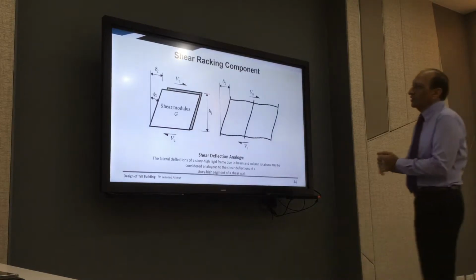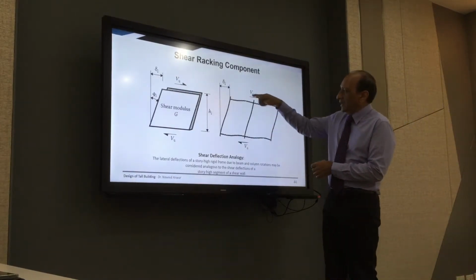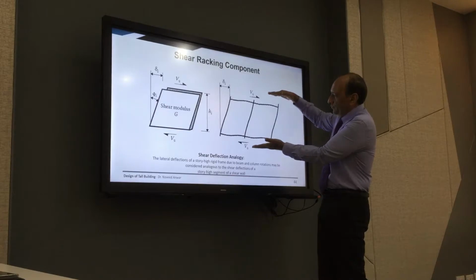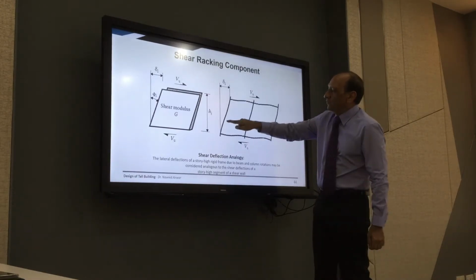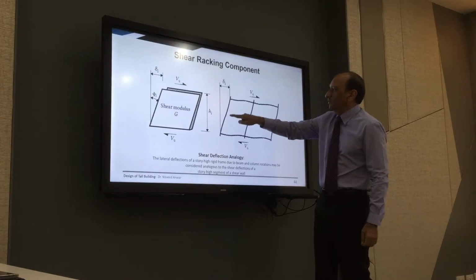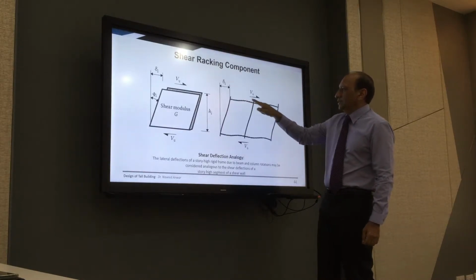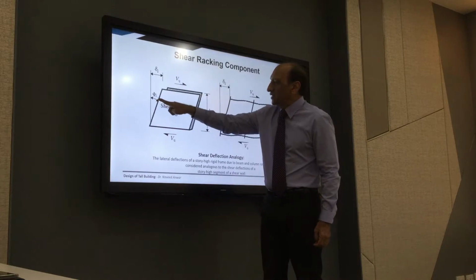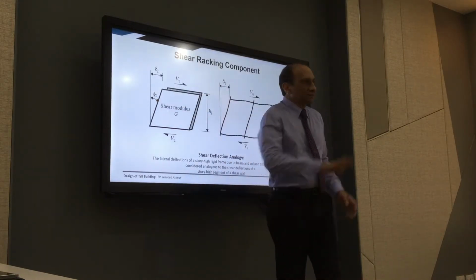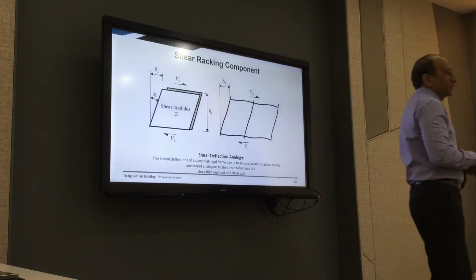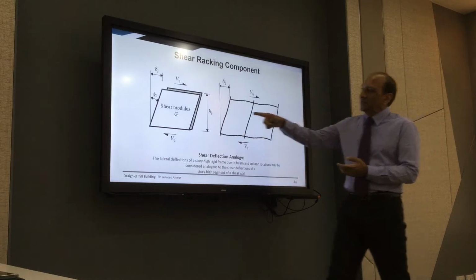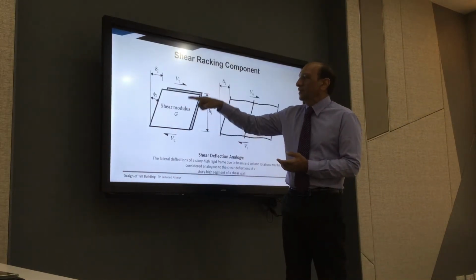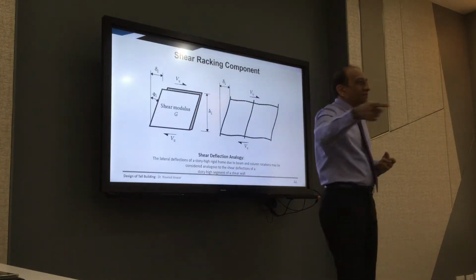And because of the drift, everything comes later. And drift is caused by horizontal forces, shear forces. So shear force causes this drift. This drift causes shear force in the column, which causes bending moment and so on. This drift causes the change of angle, shear deformation in shear walls, which causes internal stresses, which also then causes tension, compression, and shear, which causes ultimately what?